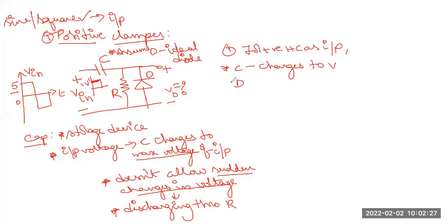Then what about the state of the diode? So positive voltage, right? So the diode is receiving plus here, minus here. So what is the state of the diode? On? Off, ma'am. The diode is reverse biased because it is encountering first a cathode, and the cathode is receiving a positive voltage. So the diode will be reverse biased. So it is in off state, isn't it? It is in off state.